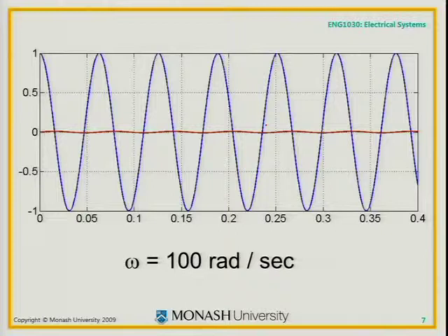But if you try and change frequency quickly, V equals L times di/dt, the voltage on the inductor is going to increase as you increase the frequency. And that means the voltage on the resistor has to decrease. Still got Kirchhoff's voltage law around the loop. So as you try to increase the frequency, the inductor chokes the current, sometimes called a choke, an inductor.